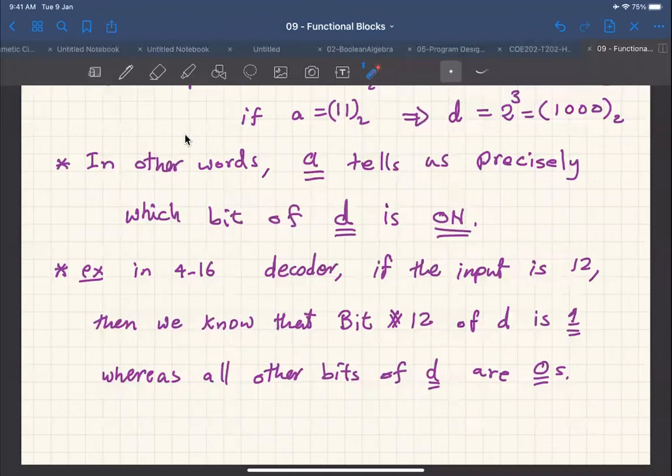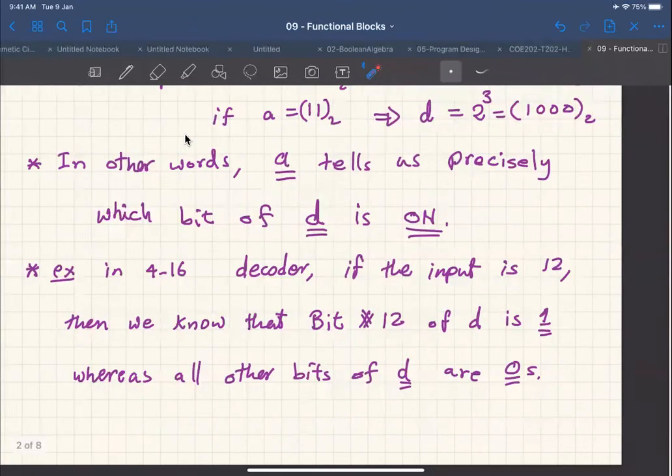I'm not talking about input. 4 bits is fine for input. But how many outputs do you have for a BCD? 16? No, not 16. It should be 10. Exactly 10, because your input does not exceed 9. So the maximum input is 9. If you get more than 9, then this is beyond your capability, and you shouldn't output that. You should blame whoever supplied this input to you.